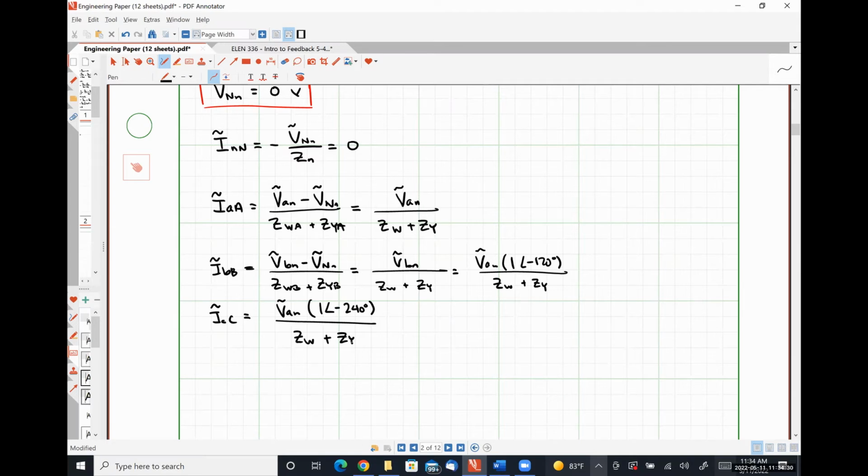It hits and starts, it speeds up and slows down because it's not getting that supply that you would expect. The exact same thing is going to happen on the system. That's also how they identify where outages occur, because everything looked reasonably balanced and then you get a sudden unbalance. That unbalance tells you the location or the relative location of where something must have happened to unbalance the system.